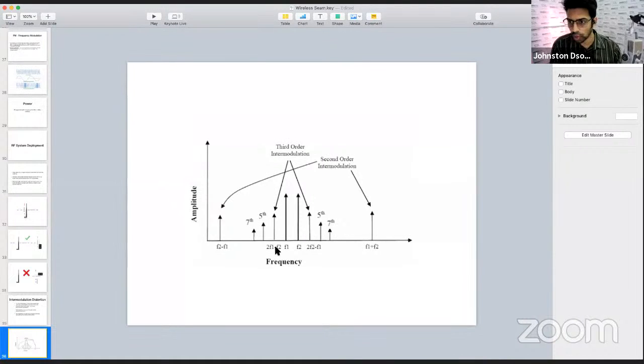So you can see a small bar that is moving. It is basically doing a scan. Now it's checking out which frequencies are free to use. So it will take like 30 seconds. Once that is done, it is almost done now. Okay, now it is telling me bank one, there are 12 free frequencies.